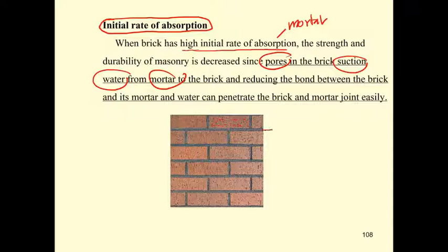So what happens is this mortar will not have enough water for the hydration process. The hydration process is going to be down, since the water is sucked out of the mortar, and that's going to reduce the bond between the brick and the mortar, and also it will let water penetrate the joints easily.